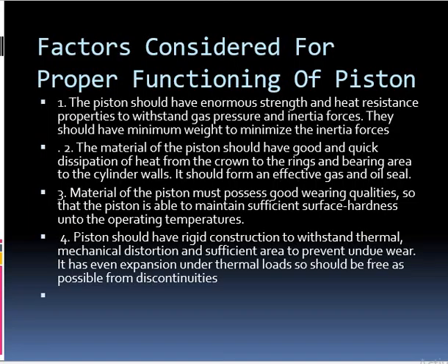Another factor to be considered is the material of the piston. It should possess good wearing qualities, and the piston should maintain sufficient surface hardness up to operating temperatures. Another consideration for the design: the piston should have rigid construction to withstand thermal and mechanical distortion, and sufficient area to prevent undue wear. It has to expand under thermal load and should be as free as possible from discontinuity.